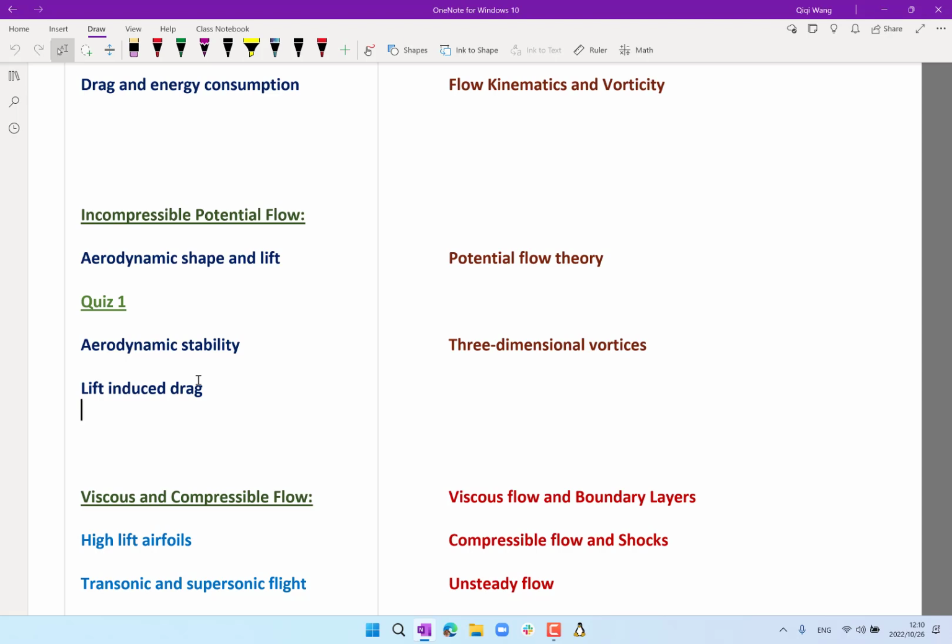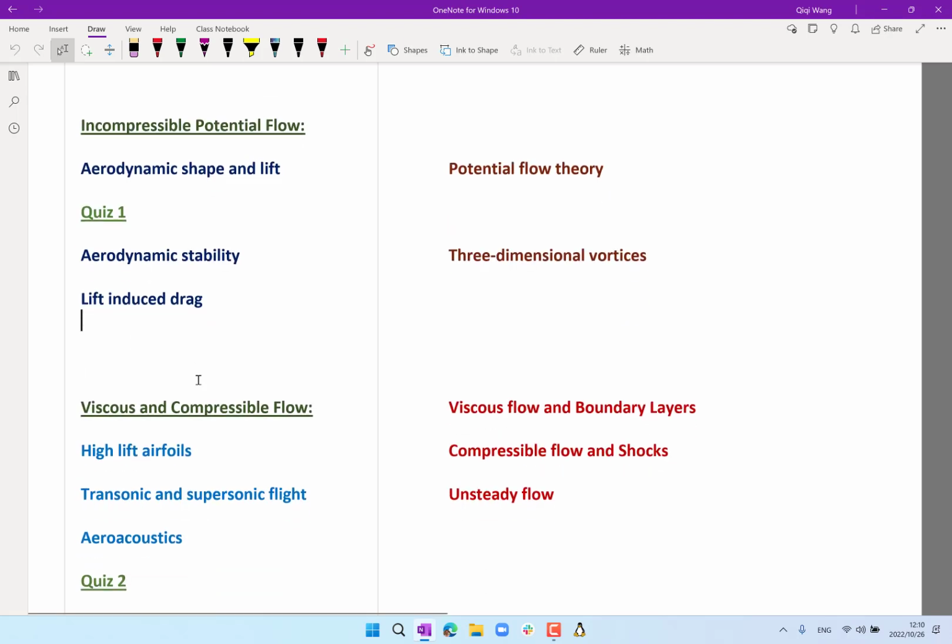It's actually the same thing for the hovering helicopter we just analyzed. We figured out how much power the helicopter has to provide to feed the amount of kinetic energy that leaves the helicopter, that goes downward in this case. So this is my most intuitive way of thinking about induced drag or power, not just for airplanes but for helicopters, and combinations of airplanes and helicopters if you think about more interesting designs.